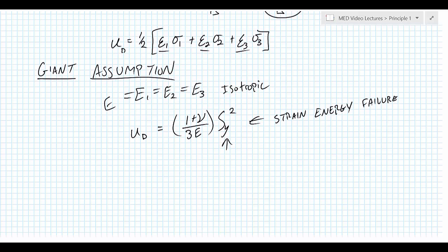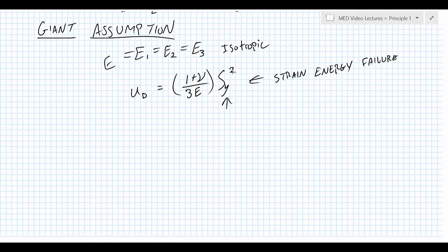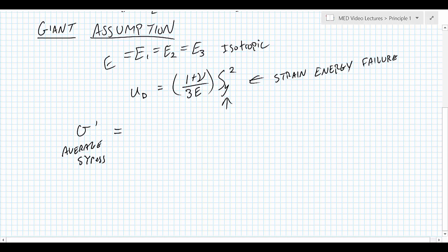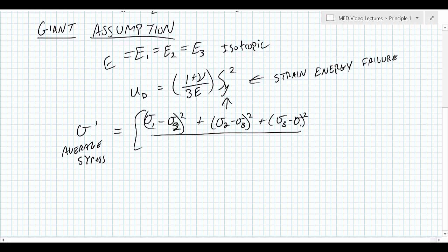So what that results in is us coming up with a generic stress state called von Mises stress, this average stress, that is a relation of the principal stresses. So we'll do the difference of the principal stresses squared, and all of that over 2. And then the square root, because we're looking for the square root from finding that squared stress value.